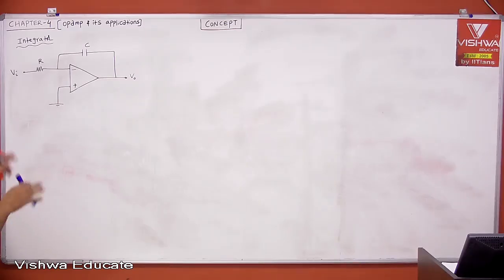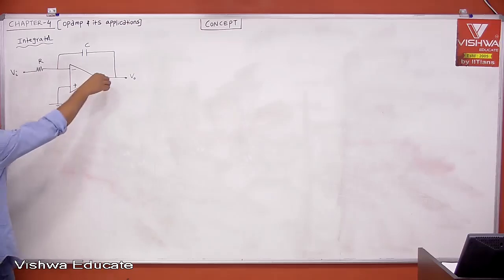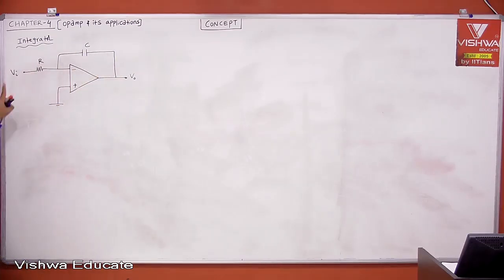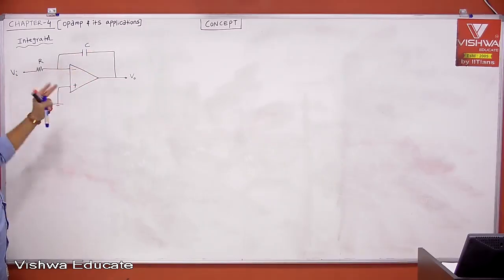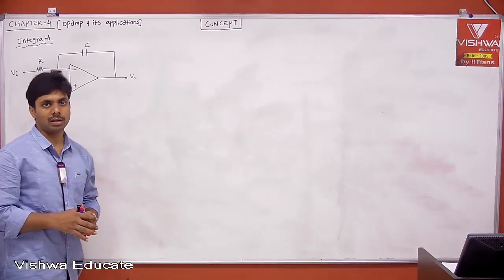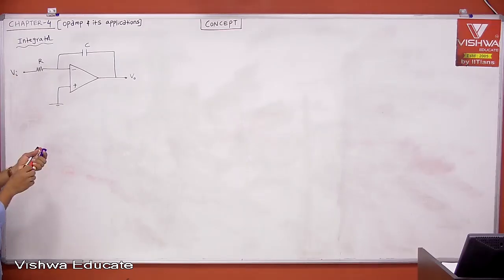Okay. Now, negative feedback or positive feedback, you treat this as an Opamp problem. It is negative feedback, because you are sampling the output and then feeding it to the negative terminal, right? Provided the input has some non-zero frequency. Else your capacitor is open. When the capacitor is open, remember it is an open loop Opamp, then the virtual ground concept is not valid, it is nothing but a comparator, right?